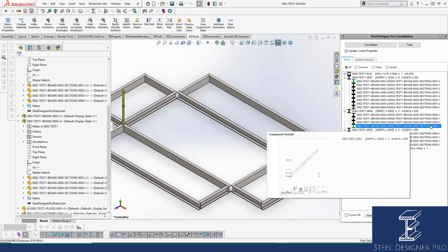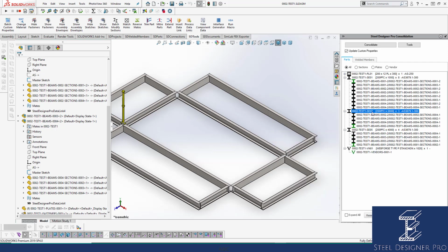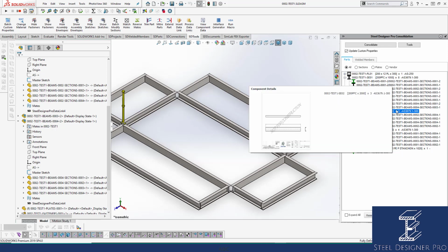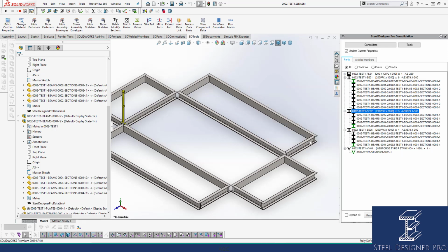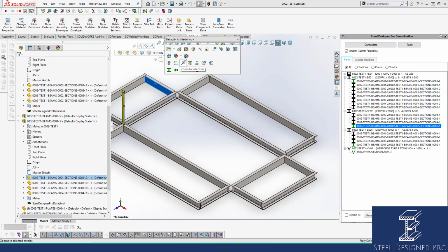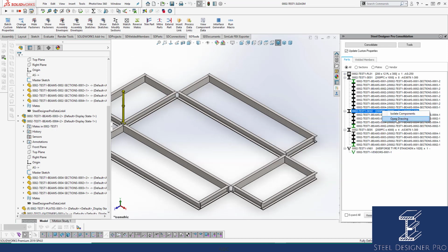And if I open the drawing up from here, it will always open up the parent drawing. Now, if the parent drawing is the one that you open, that's the drawing that is going to be dominant in all cases if you come over here and right mouse click and open. And it will then go to all the children, which are these ones that do not have a green icon, and update those drawings. Yes, you can open it this way, no problem, and save it. It'll update all the others, but it's best that you open it from here.